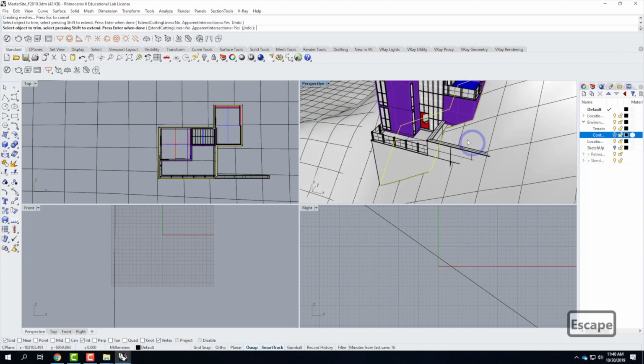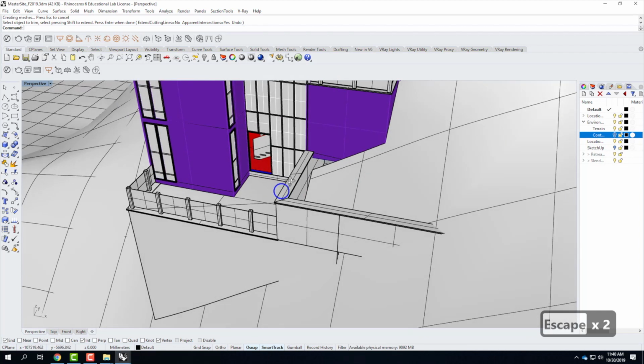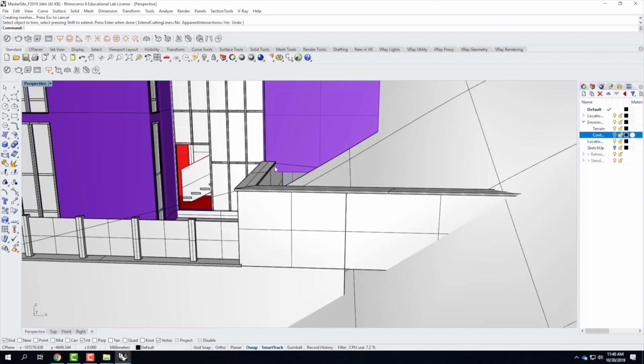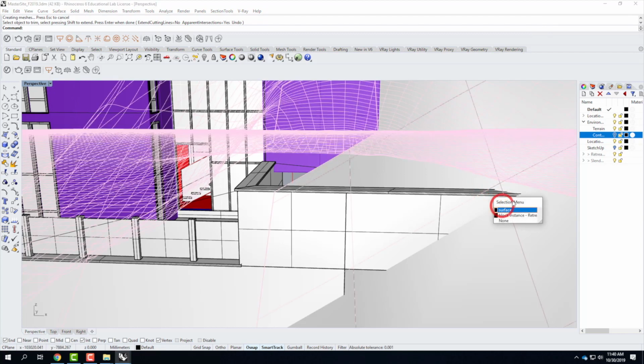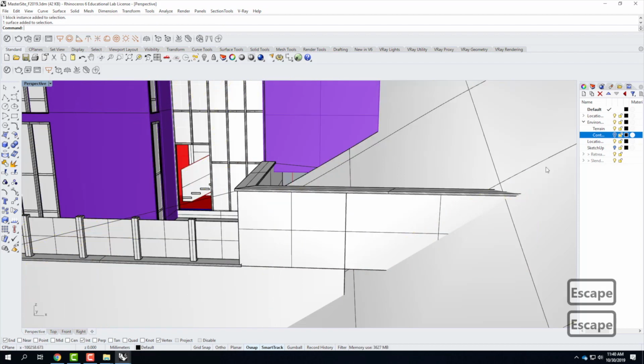The next step, though, is I needed to somehow solve how this area was going to be incorporated. For me, I wanted the slope to soften out as it gets closer to this little retaining wall, as opposed to staying quite so steep. So I want to adjust the slope a little bit. Part of the reason that I chose to set this one up was so that you guys could see how you can adjust the terrain as necessary. So what I need is first the intersection between this block here and where this surface would be. I need a little line right there.